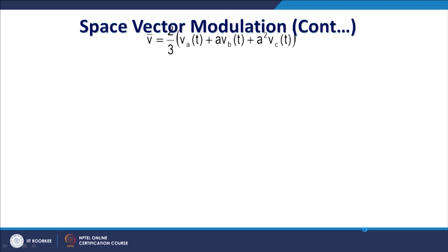This is the average voltage to be fed, and you can see that if you add these up, the summation gives 0. For this reason your common mode voltage gets eliminated. It is the same concept that has been used in the case of third harmonic injection, where we can also offer the NN voltage, or common mode voltage, as 0, and thus this voltage gets eliminated.